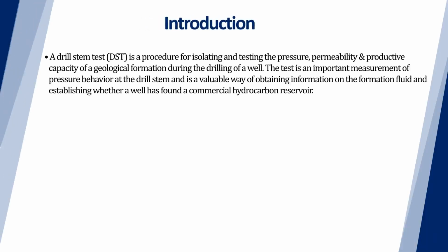A Drillstem test, or DST, is a procedure for isolating and testing the pressure, permeability and productive capacity of a geological formation during the drilling of a well. The test is an important measurement of pressure behavior at the drill stem and is a valuable way of obtaining information on the formation fluid and establishing whether a well has found a commercial hydrocarbon reservoir.